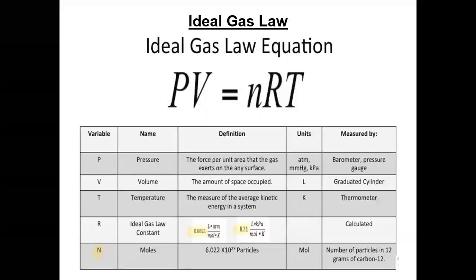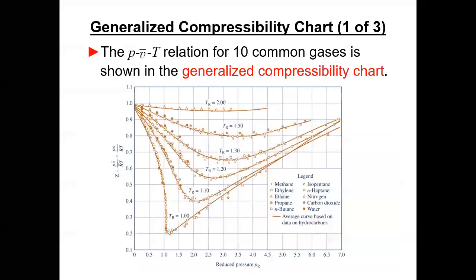We'll review all of this in some detail. But anyway, I wanted to throw that up there. So that's the standard ideal gas law. P little v is equal to RT, or P big V is equal to nRT. And I think you all are familiar with that from good old days in chemistry and high school and all that kind of stuff. Okay, well, have y'all seen a compressibility factor chart?